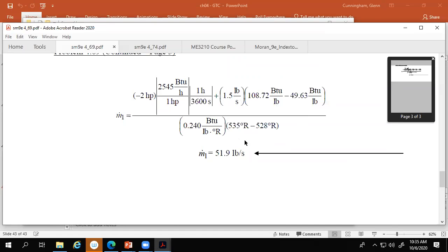But if I'm given Fahrenheit and I'm going to subtract two Fahrenheits, if I add 460 to one, I add 460 to the other, I subtract, the 460s go away, and I get the same temperature difference. But when you go to the ideal gas law, you're just plugging in one temperature. Well, it makes a big difference if you're just plugging in one temperature than if you're doing a delta T. So for delta T's, you can do Fahrenheit or Rankine, and you'll get the same answer.